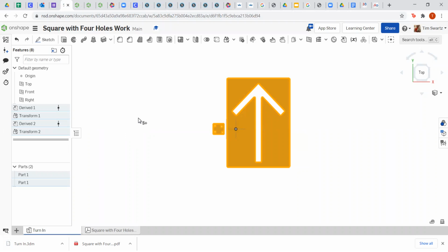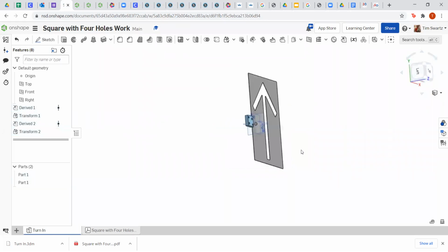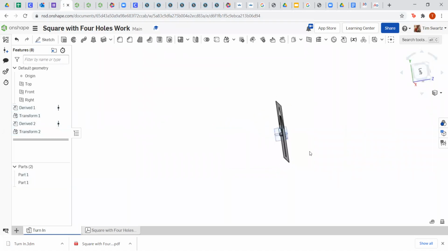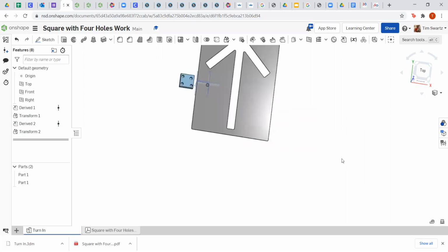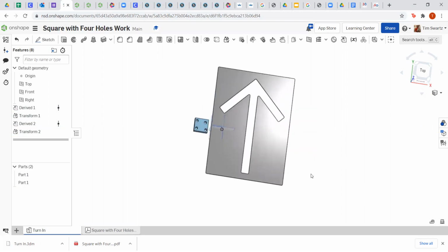And then you can just open up that Rhino file and it should have all of the kids' projects here. And they are all in 3D. So when you get into Rhino, you can just select everything and use the command make 2D, and then you'll have 2D profiles for all of the parts here. So that can be a simple workflow for you guys that allows students to do this remotely through Onshape. And when you get to Rhino, it's not too much work to convert it over.